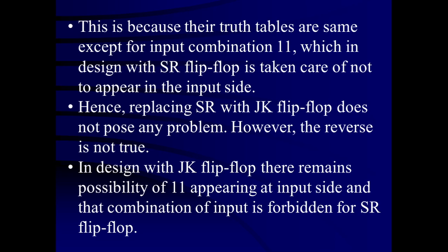However, the reverse is not true. You cannot make a reverse here. If you have designed with the JK flip-flop, you cannot directly utilize the SR flip-flop for that. It has to be modified somehow. In a design with the JK flip-flop, there remains the possibility of 1-1 appearing at the input side, and that combination of inputs is forbidden for the SR flip-flop.